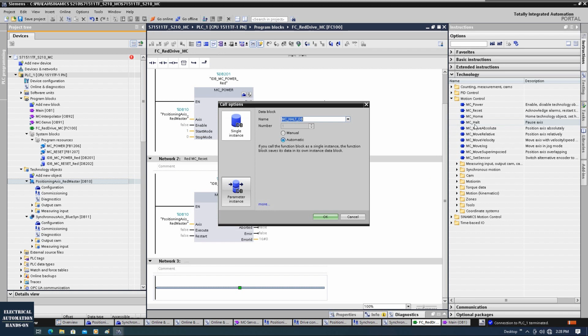And after you trigger the halt, if there's another command to fire this motor to move, then the motor will move. The command of the halt is only used to temporarily pause the axis. If there's a new command to move, the axis will move. So this is the key difference between the halt and the stop. The stop command can keep holding the axis, but the halt is just a temporary pause of the axis.